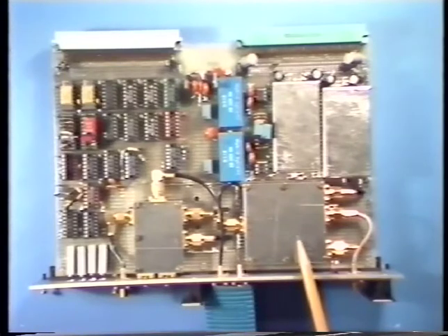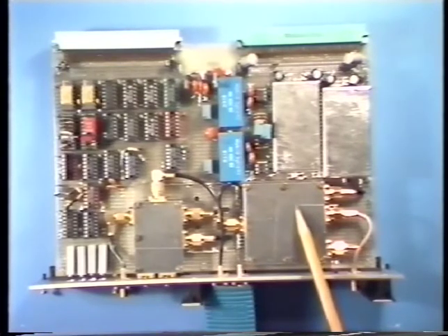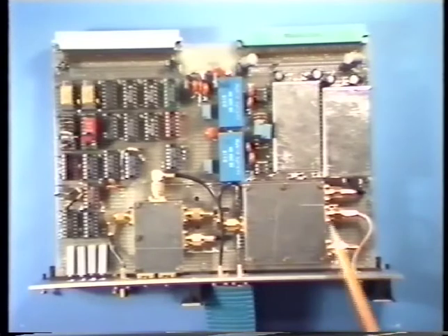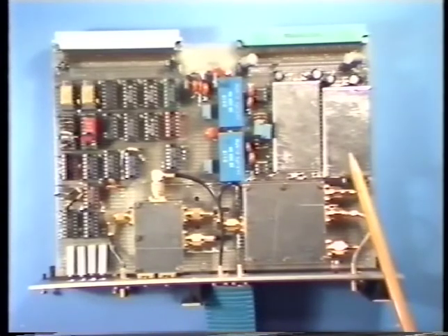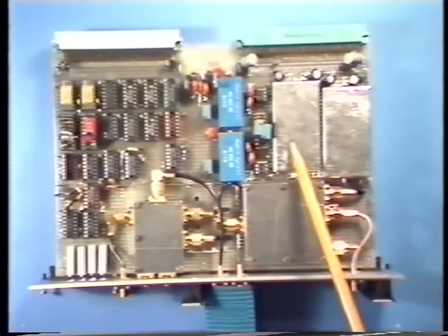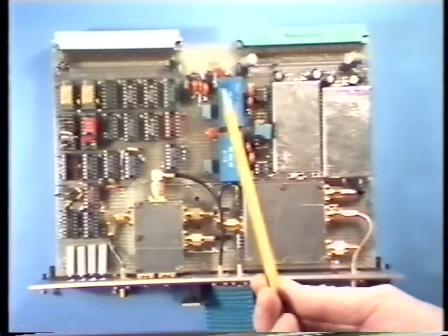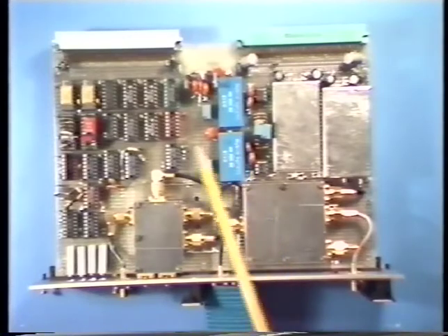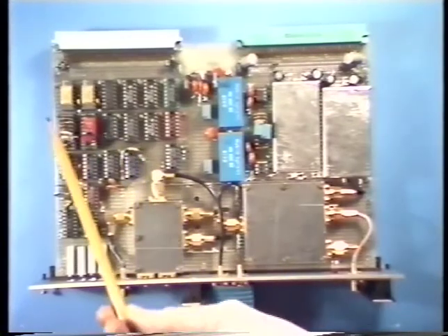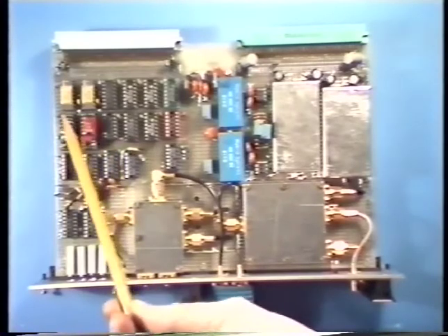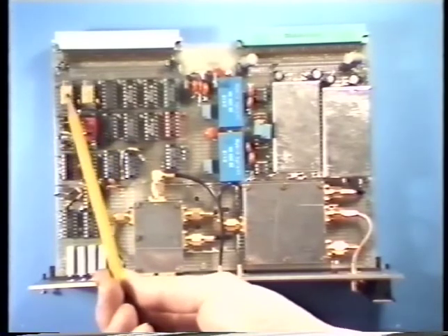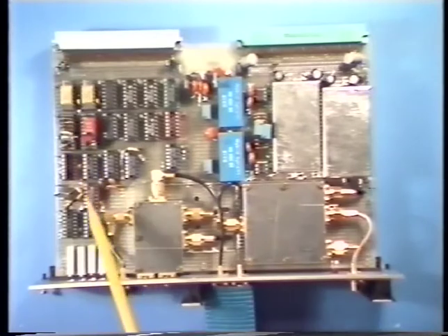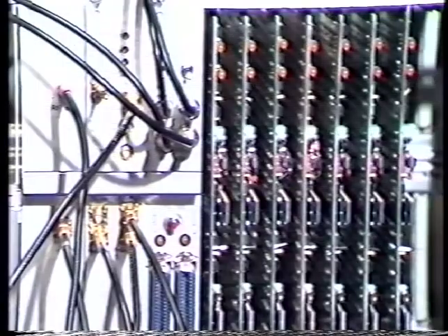This is in-phase and quadrature demodulation at 70 MHz, periodic side lobe suppression filters, which are analog, AD conversion, and circuits for clock control under control of DA converters.